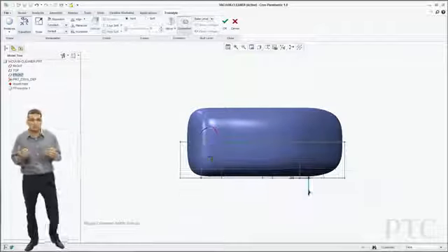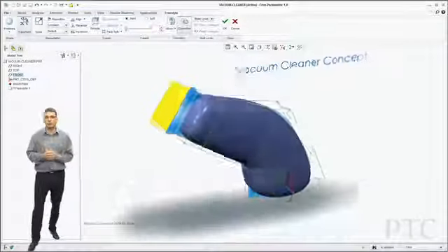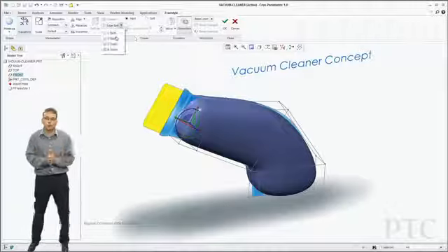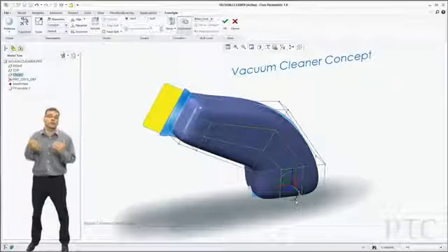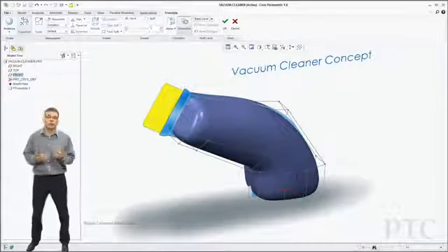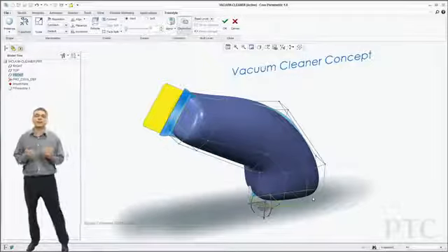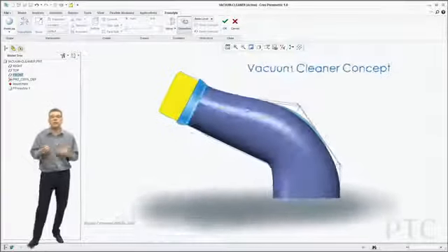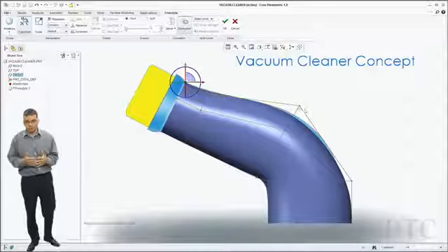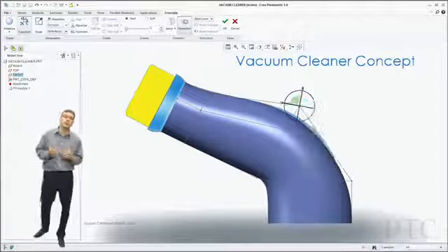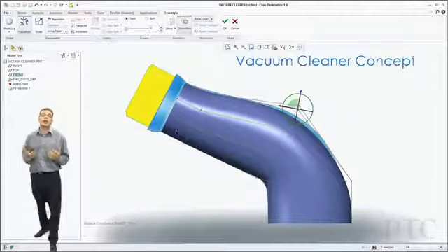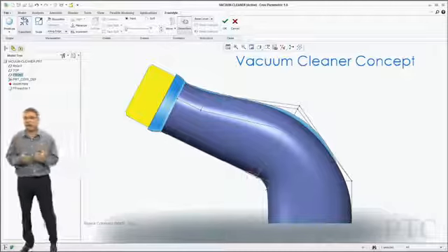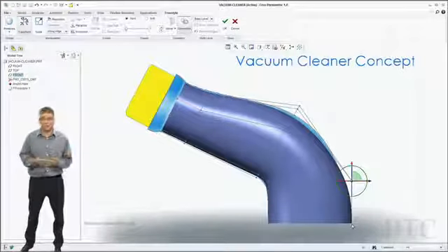Now the product right now is looking a little bit too chunky, so I'm going to squash it in a little bit. In addition, the product's going to be symmetrical, so I'm going to turn on symmetry. I can simply select the mirror plane that I want, and half my control mesh disappears. The top and bottom ends of the shape, I want to have open. So to do that, I can simply select the faces and delete them.